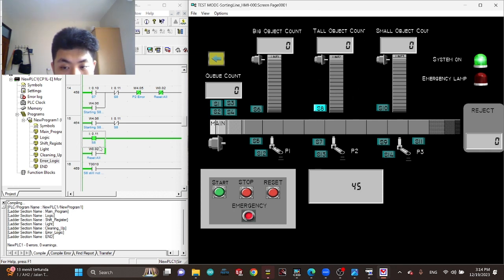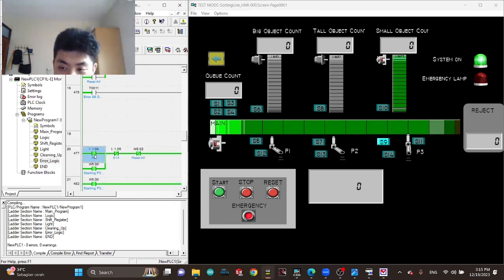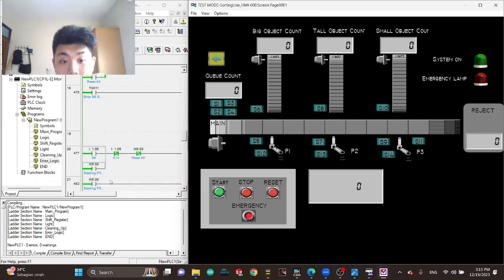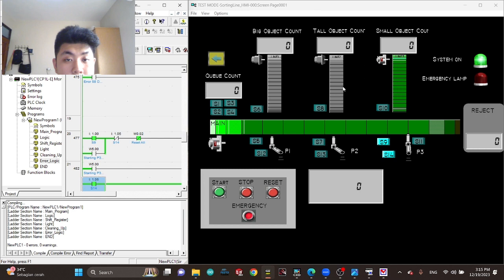The next one is the error code that happened at S9, which is also the same as S5 and S7, where the product is detected and is supposed to be pushed, but the piston doesn't move. And then S14 is also similar to S12 and S13, where it is moving, but it's stuck in there.